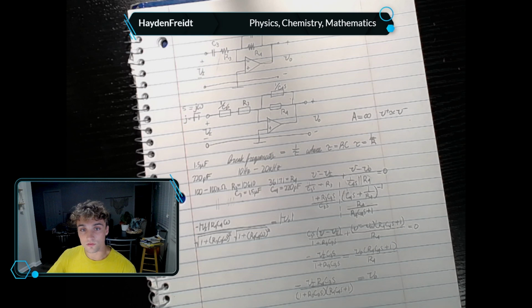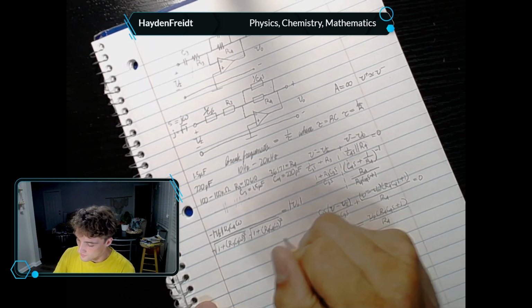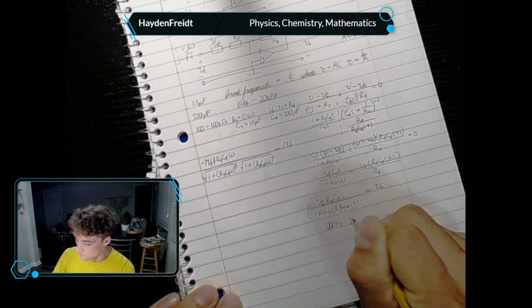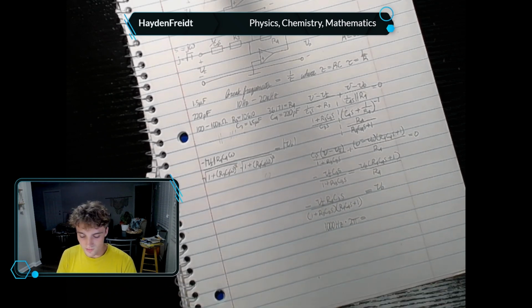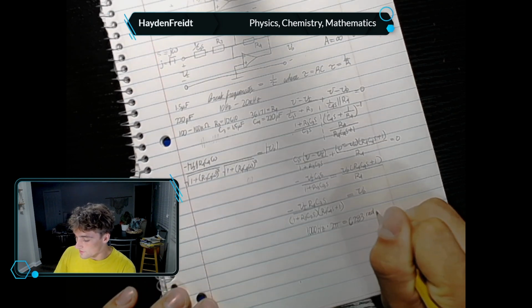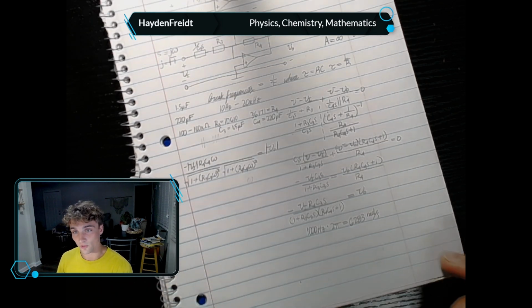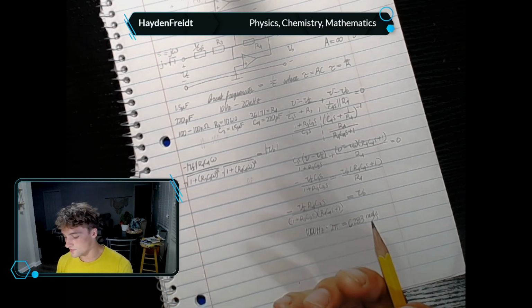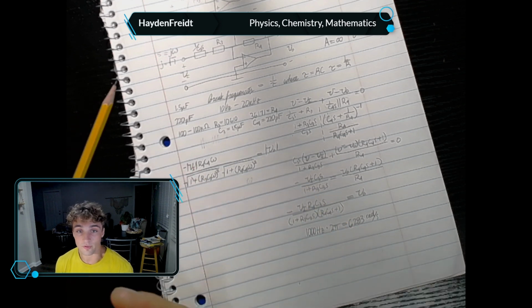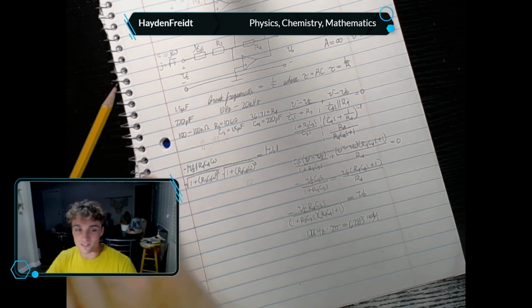Last time, we wanted a gain of 2 at the mid-band frequency around 1000 hertz, 1 kilohertz. Again, to get our omega, 1000 hertz times 2 pi is going to give us our angular frequency, which is 6,000 something. 6283 radians per second. This is what we're going to plug in for omega here. We're going to see the outcome for some arbitrary value of V_in, which I'm going to pick. I'm just going to go with 5 volts.